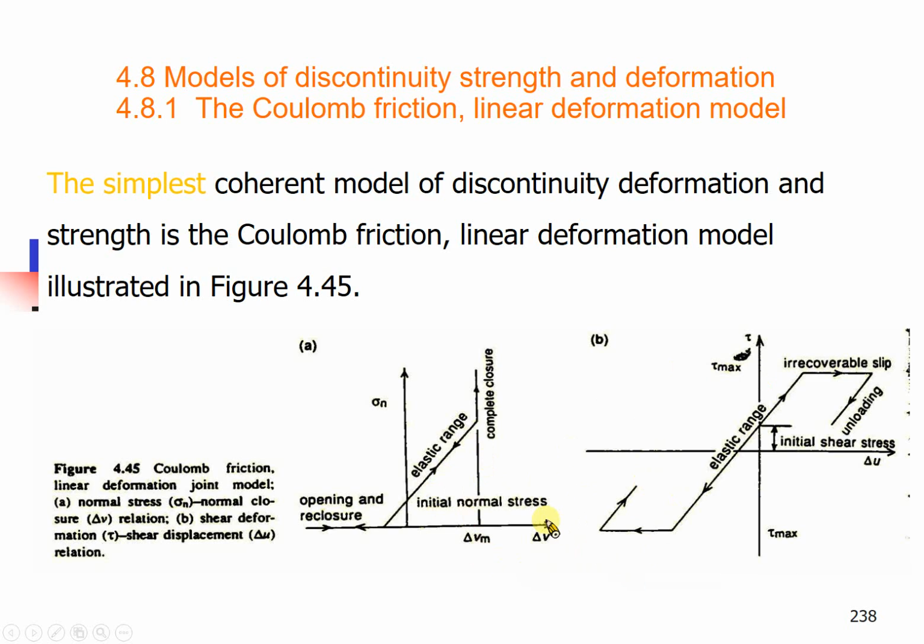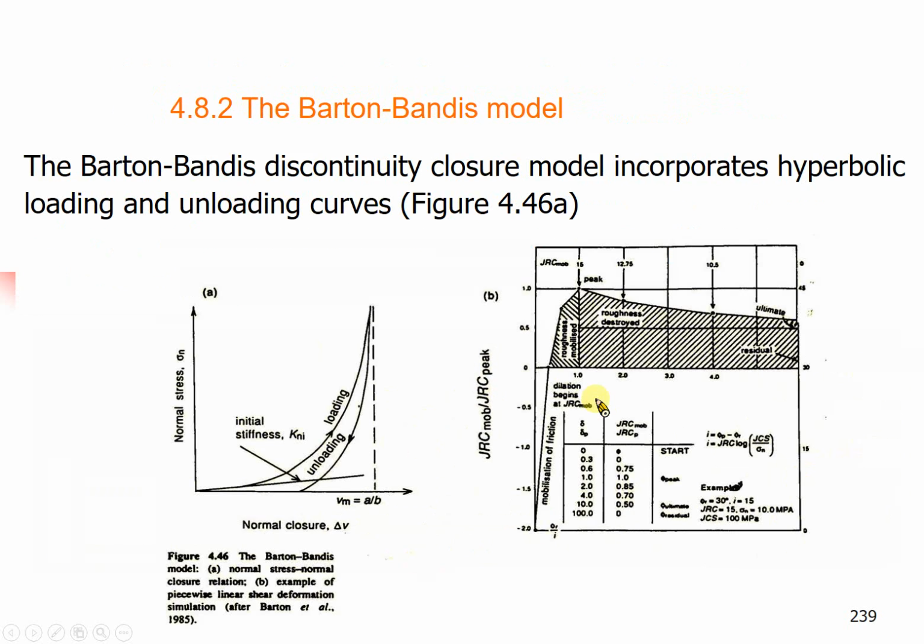Okay, in soil mechanics, or also in rock mechanics, we always need to have the constitutive law or constitutive equation to make the calculation for finite element analysis or finite difference analysis. Numerical simulation, we always need to have the constitutive law. So this will be the kind of constitutive law of discontinuities. Okay, so this will be the real case, loading, unloading. And this will be a famous model proposed by Barton and Bandis. So this will be a curve.